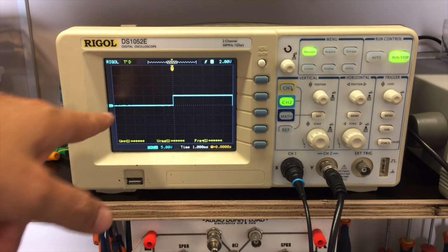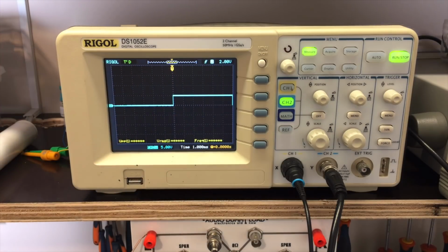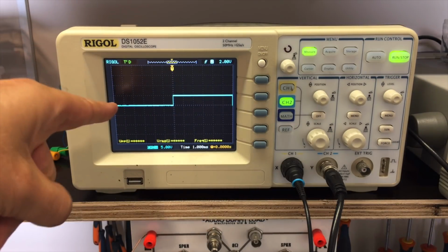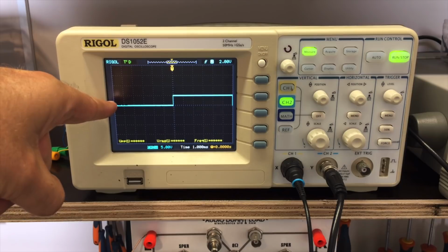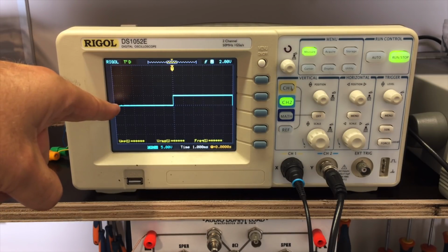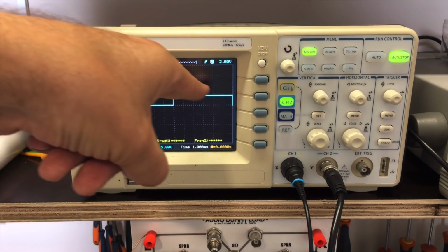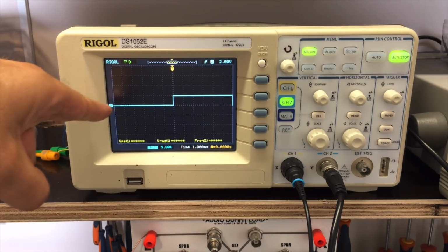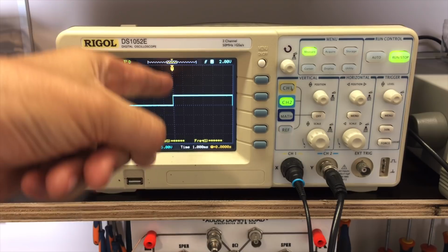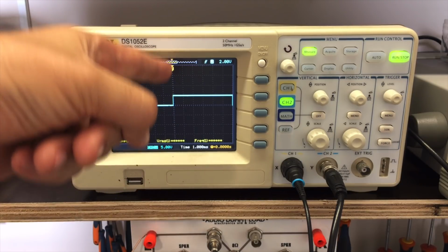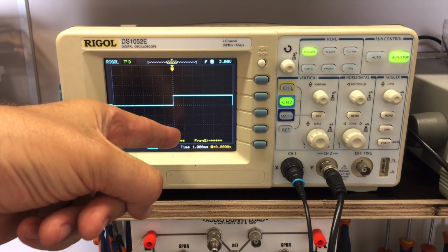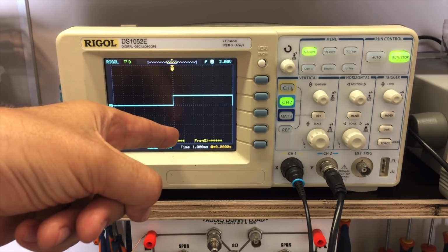Okay? So this way I get the entire wave across here. And this means that the sweep is starting here at 448 kilohertz, and it goes across, and it ends here at 472, and then it starts there again. And I know then that the middle, because it's a linear sweep, the middle will be exactly 460 kilohertz.